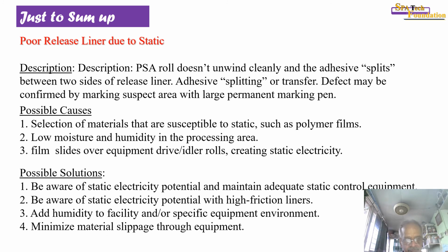The possible solutions: be aware of static electricity potential and maintain adequate static control equipment. Be aware of static electricity potential with high friction liners. Add humidity to the facility and/or specific equipment environment. Minimize material slippage through equipment.